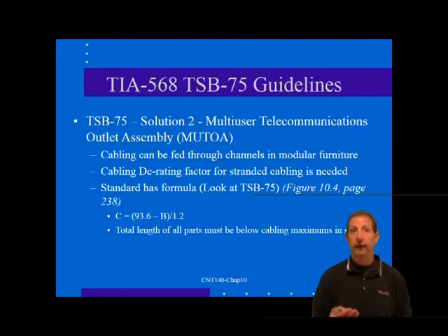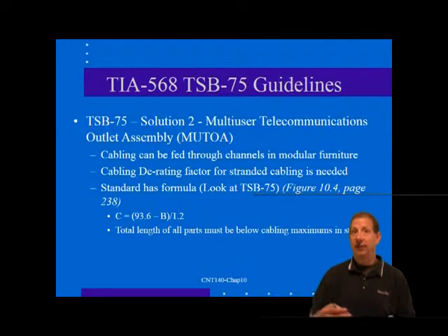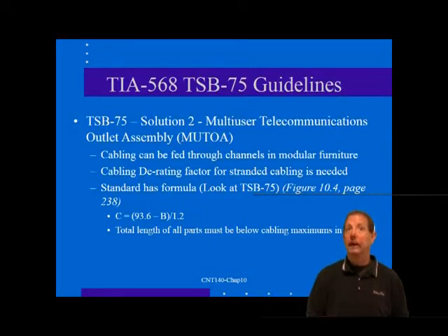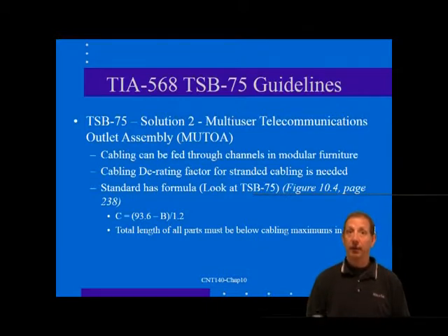Excess user cord length. The other issue that must be dealt with is the excess cable that will be left over. Now, unlike horizontal cable, which must be trimmed to within 18 inches of excess cable at the workstation outlet, the user cords are normally fixed length, manufactured cords. Cat 5e, 6 or A6 field termination of stranded cable into modular plugs may be outside the ability of the average cable technician because of the narrow tolerance in the placement of the conductors from the plug. Now, if you must trim to length, follow the methods that we discussed in Chapter 9 for terminating the cable.